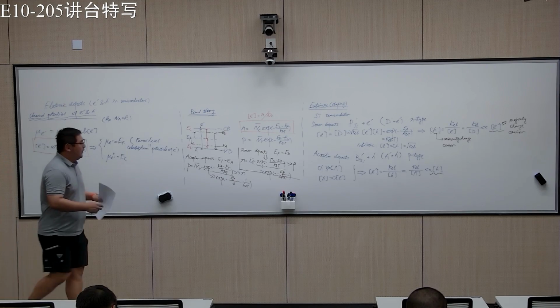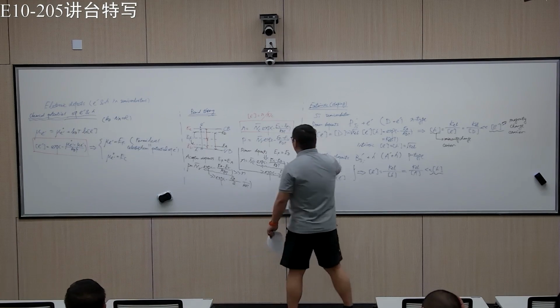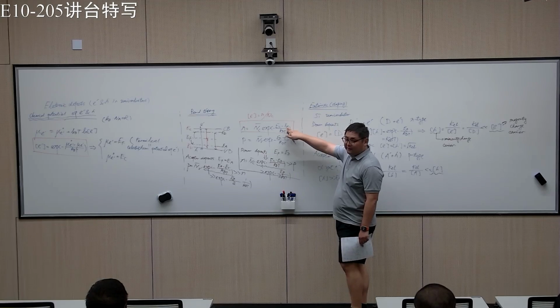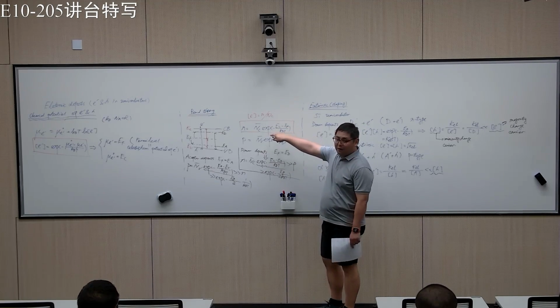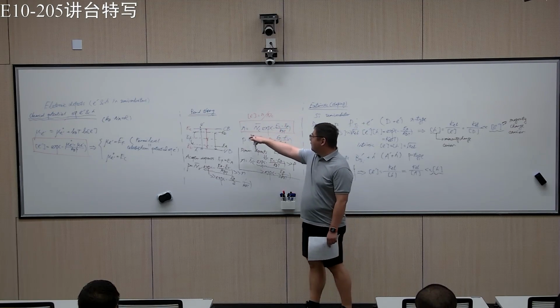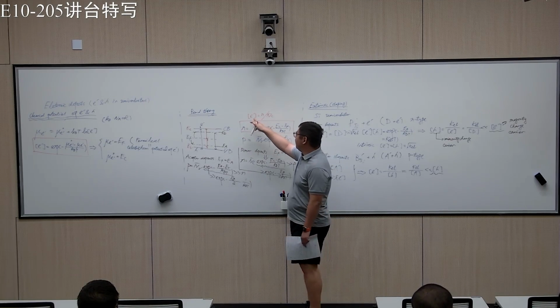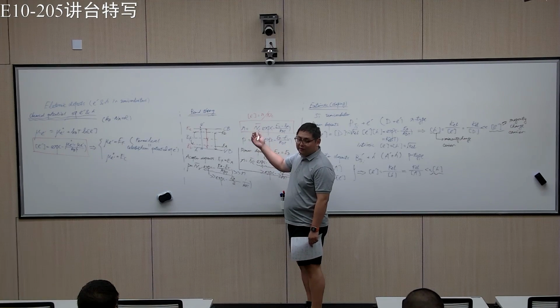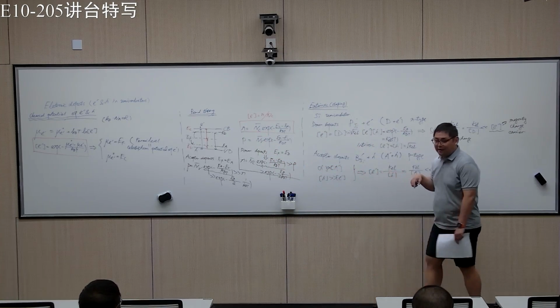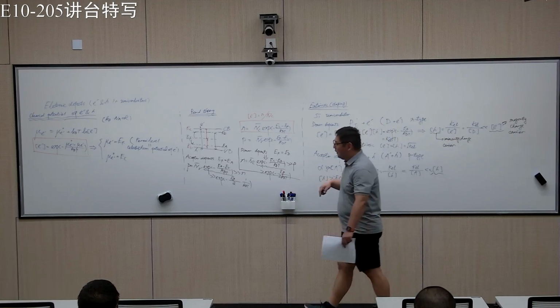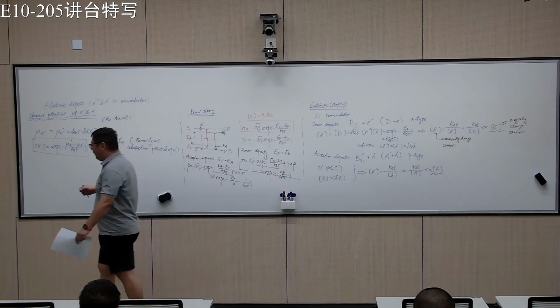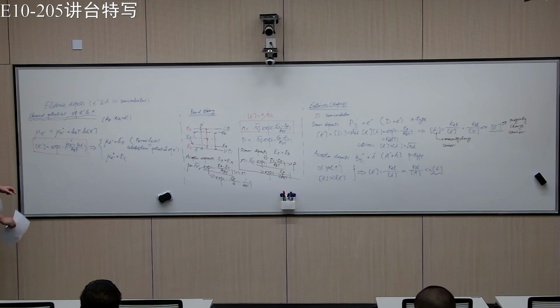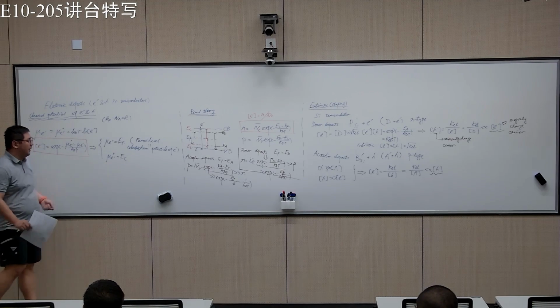You can also see that if I use this EF as EC, then this exponential part will be just 1, which means the number of electrons will be the same as this one. So every single density of states will be occupied. This is basically the definition of the standard condition, which means that you have unity of the concentration, or unity of the electron.